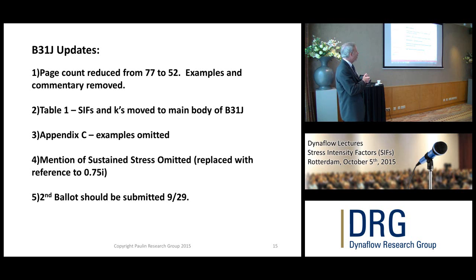Examples were taken out. And for those of you that are familiar with B31.3, you know that in 2010, it introduced the Sustained Stress Index, capital I. Everybody knows, right? Sort of. So there was a new capital I, but there was no definition of it anywhere. So it was introduced into the code and there was no definition. As we were writing this document, they said, would you please put a definition of this term in the B31J? So we did. So there was a B31.3 capital I definition in B31J.